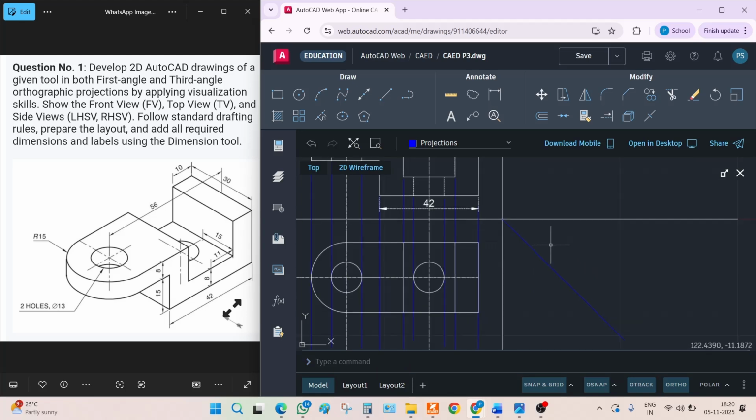So what I have to do is just draw this projection. How many projections will be there? Only at corners. Count the corners. One corner is there, two corners are there, so only two corner projections are required. After that, the circle edges and then the center line. So 1, 2, 3, 4, and 5, that is the center line. Five types of projections are required.